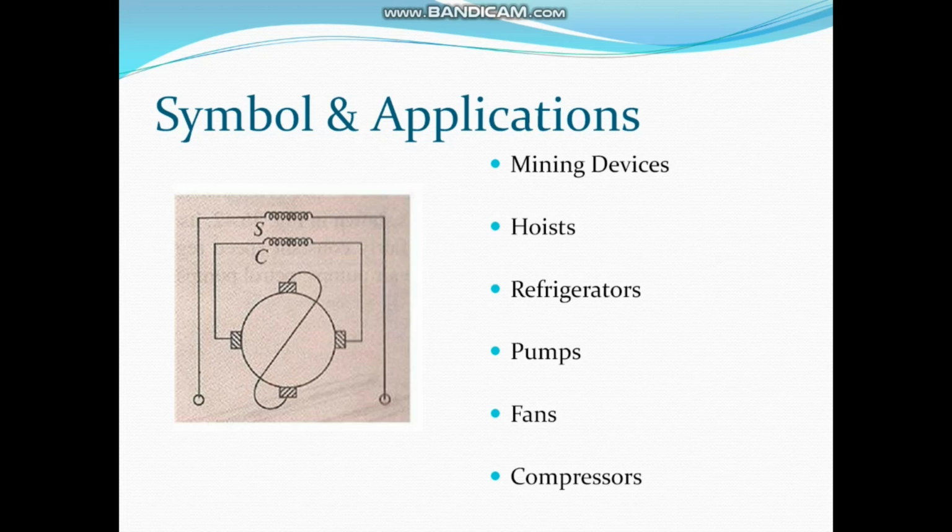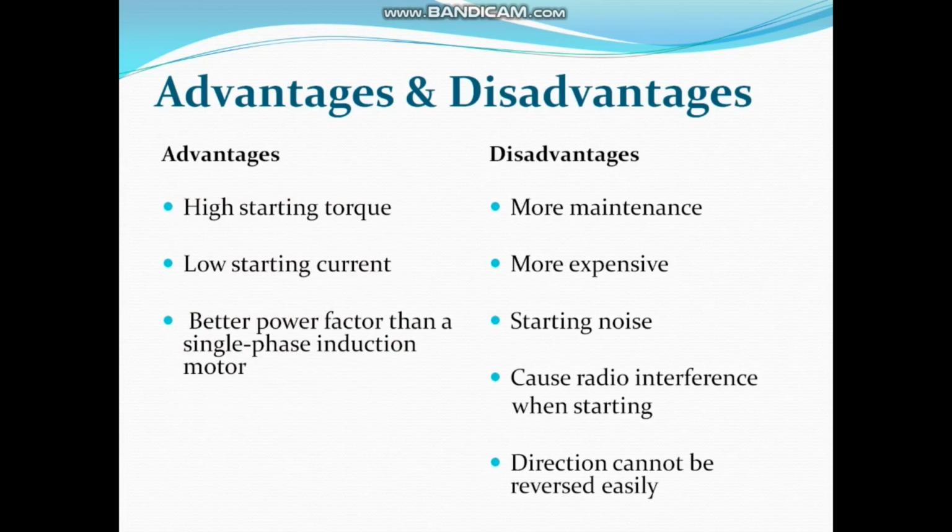The various applications include mining devices, hoists, refrigerators, pumps, fans, and compressors. The various advantages and disadvantages of the single-phase repulsion start wound rotor induction motor are: high starting torque, low starting current, and better power factor than a single-phase induction motor are its advantages.